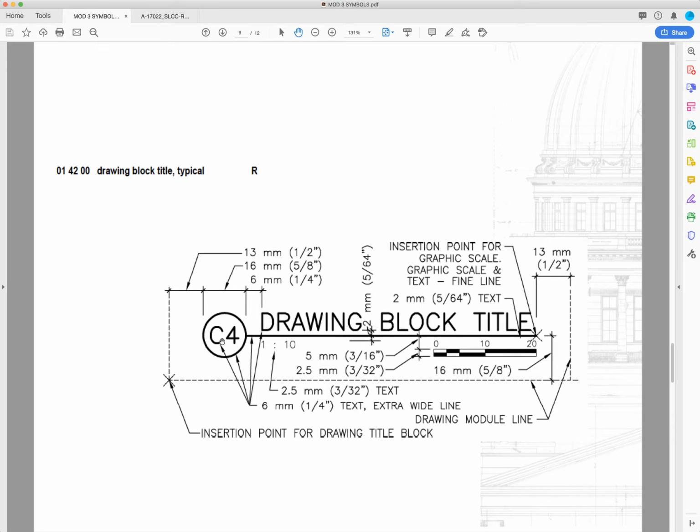So we've got the grid or the module that the drawing is on the sheet. These drawing titles are typically on your sheet. And within your sheet, you can just say what module it's on, and the actual title. So this might be first level floor plan or east elevations. And then we typically have a scale. So this is an engineering scale. This could also be 1/4 inch equals 1 foot. And then they have also chosen to include a graphic scale.